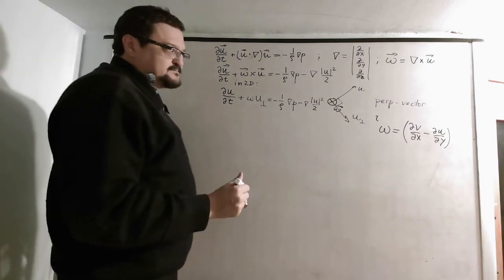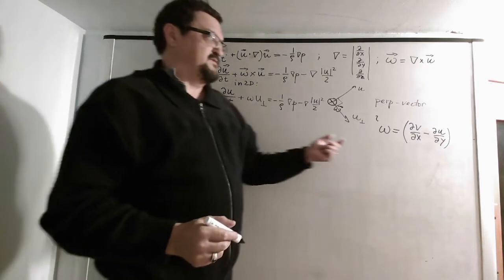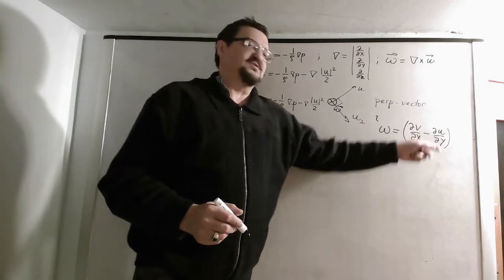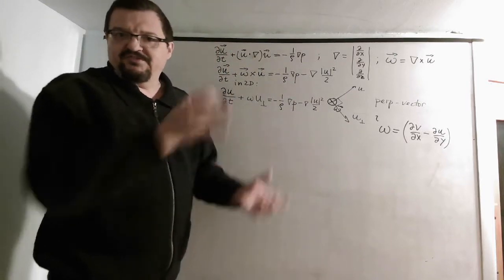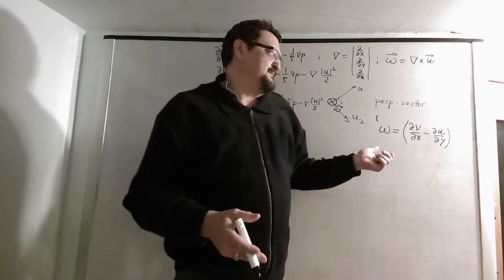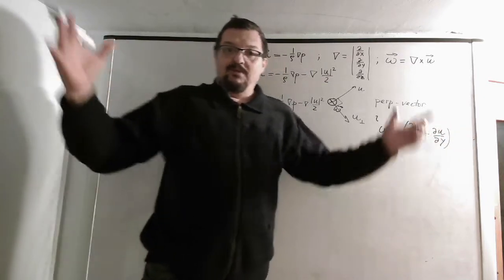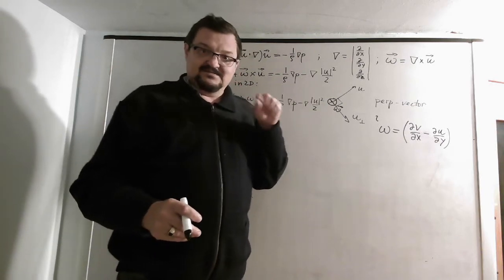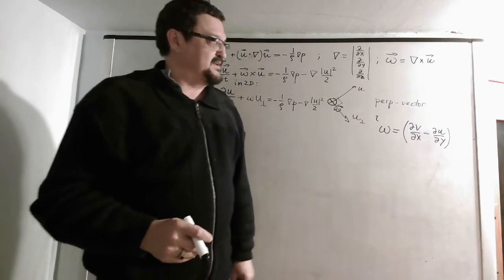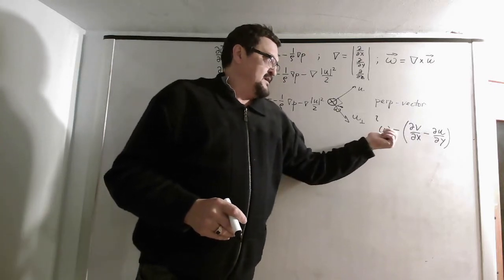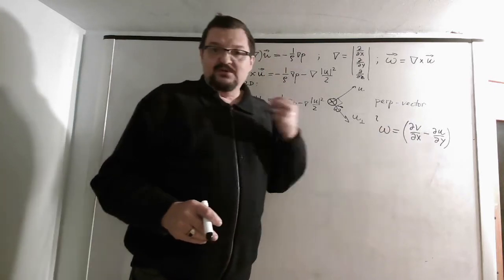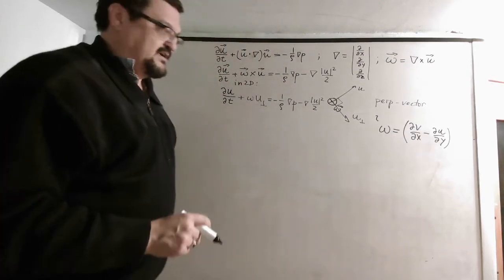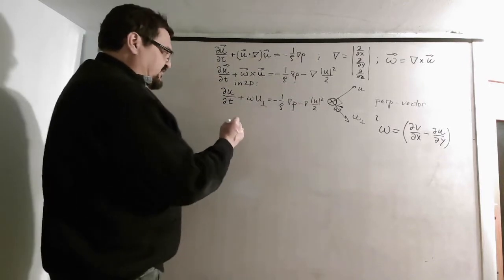and if we have a regular rectangular grid with Cartesian coordinates, then it's no problem computing these derivatives. But again, we have this arbitrary grid, and so we basically don't use a global x, y coordinate system, only a local one at this specific place. So instead of computing omega using derivatives, we will apply Green's theorem to compute it differently as a control integral. So let's apply Green's theorem.